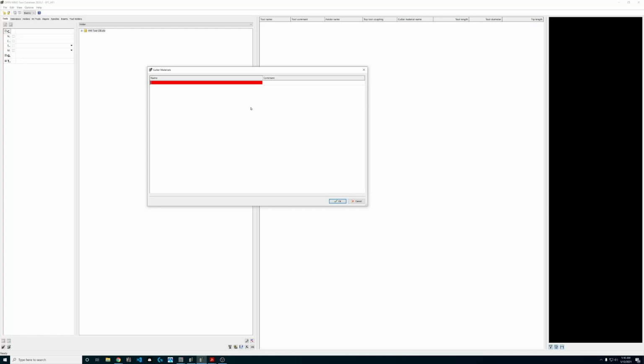So almost every major manufacturer has a list. OSG or Goering are great examples because people use those taps all the time. They might say, oh, we like list XYZ tap or list XYZ drill. Other vendors might have a name for the series. We use a lot of SGS tools. So, for an SGS tool, let me turn around and grab my catalog over here. S carb is their aluminum line, but for each S carb, there's a series 47, there's a series 43, there's a series 43 MCR. That's metric and corner radius. 43 LC, that's a long tool with a neck on it.